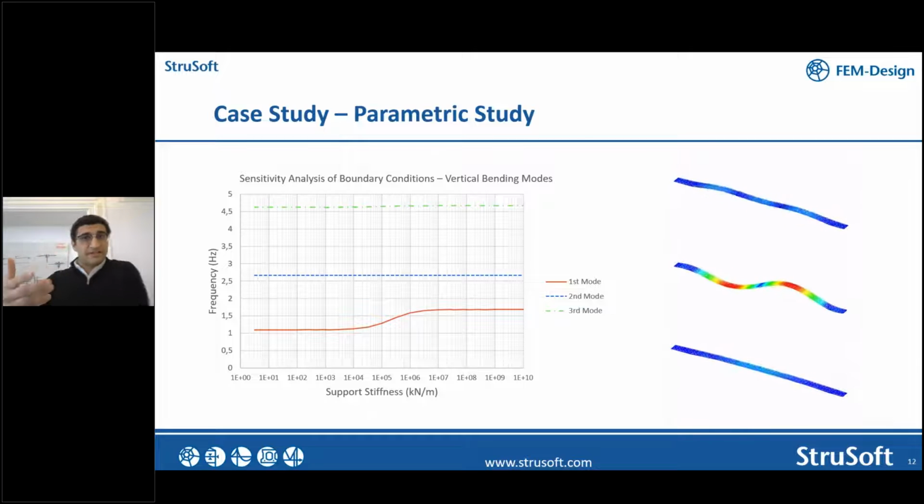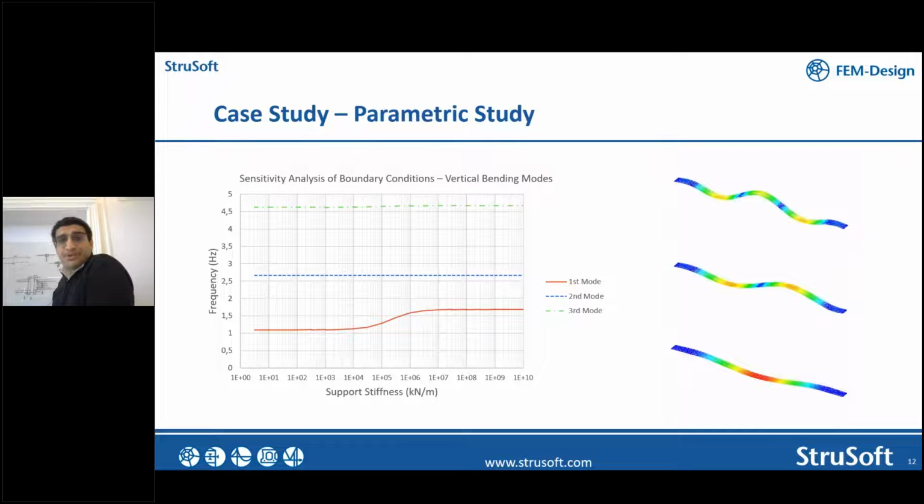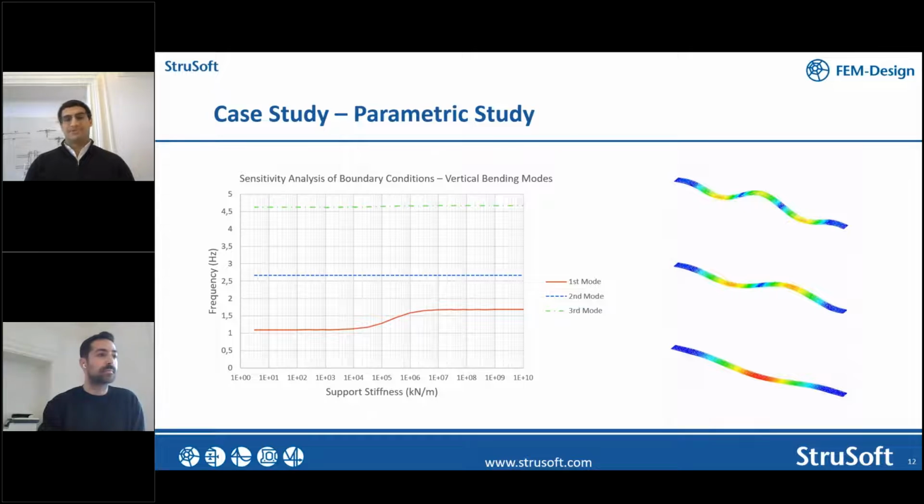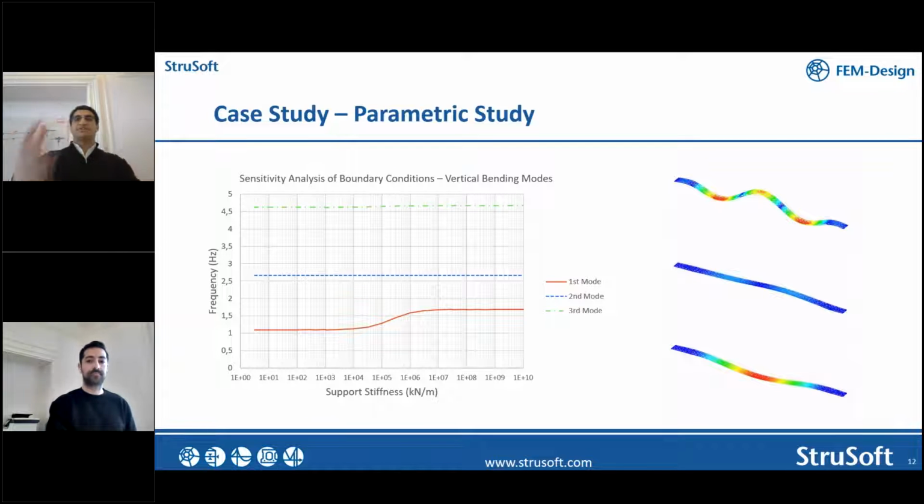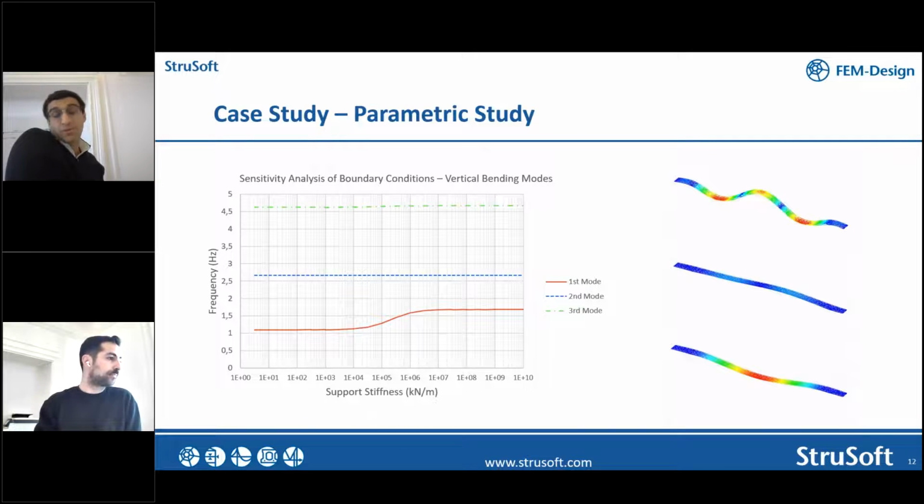As a researcher, I am pretty sure you are able to find a construction solution that gives you that boundary condition, or something closer to it, such that you improve the decision making of your model. If you use a simply supported roller for this particular bridge, that is okay for the static solution, but you would not have that. And this is where the parametric analysis becomes quite important.